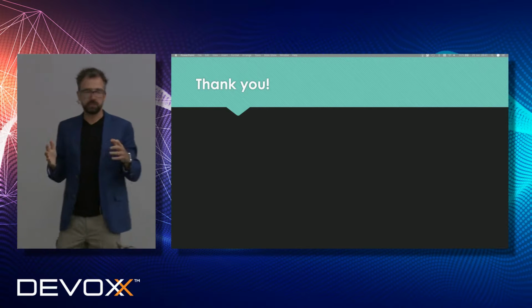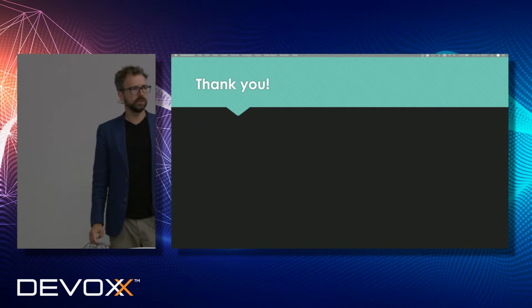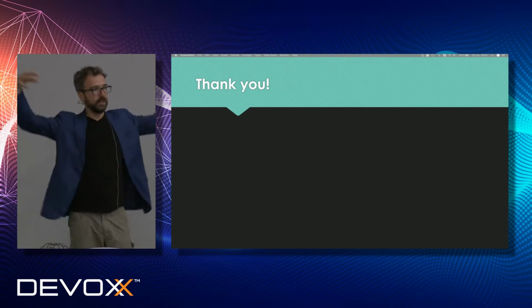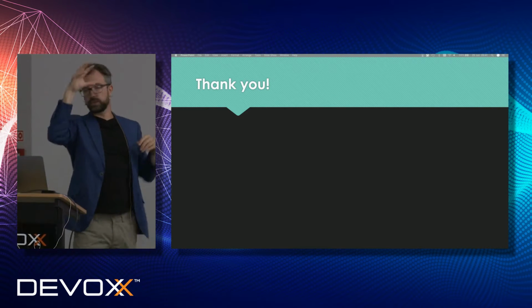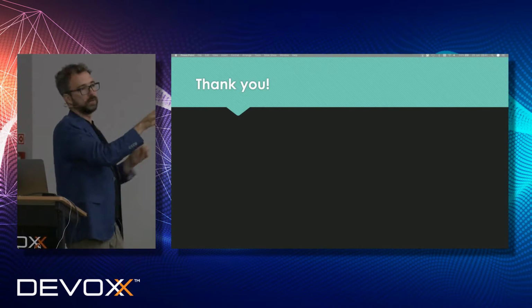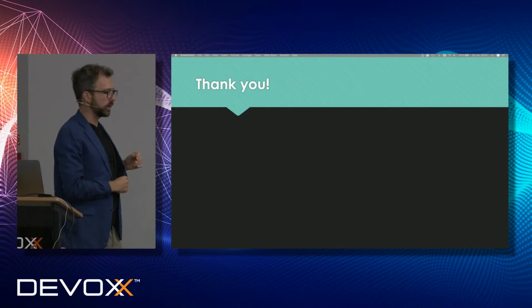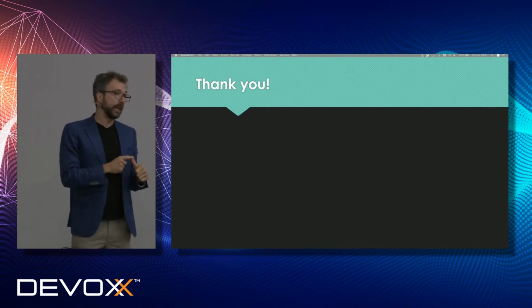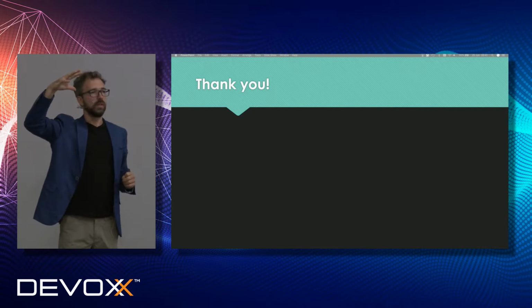You probably all know the HTC Vive, is it called? Like the VR headset. They have these satellites. Basically that's the other way, where you do an external camera and you start figuring out, based on the camera input, where the drone is. I've experimented with that a lot. It's very accurate. That's the big upside. If you do an external sensor, it's very accurate.